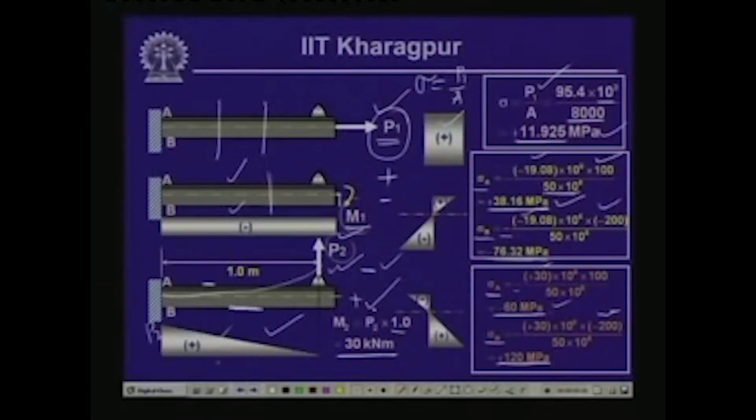with a couple. So the cantilever beam now is subjected to this axial pull which is concentric, then we have a moment, a couple acting at the tip of the beam, and we have a vertical load which is acting at a distance of 1 meter from the support, which is causing a bending in the beam. So, we have seen the 3 individual actions. Now this is a case of combined stresses.